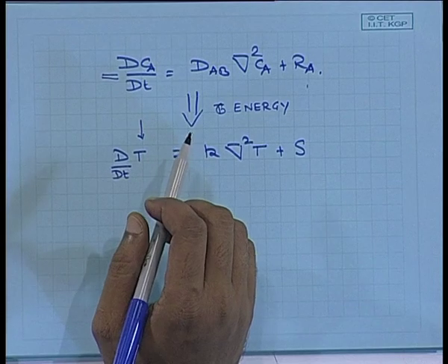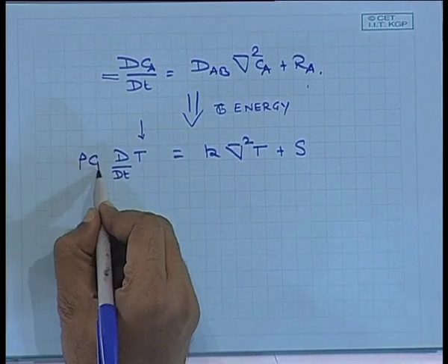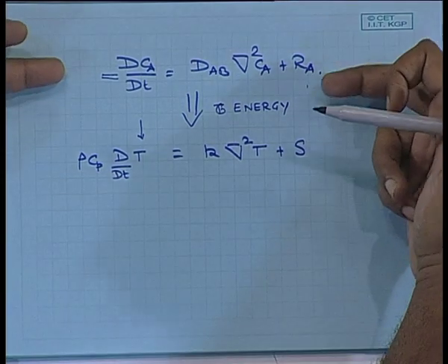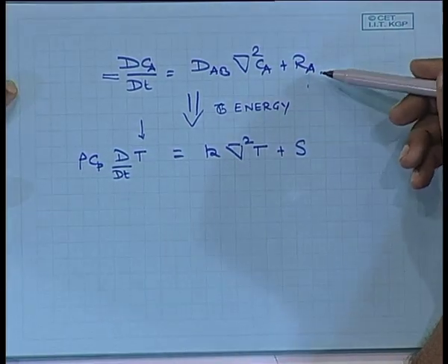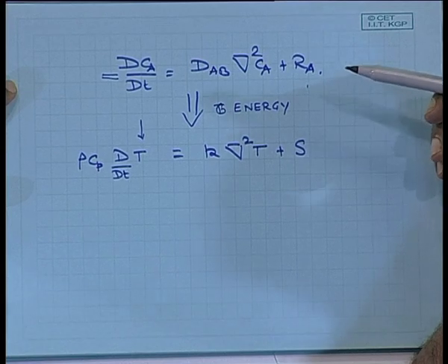So, is it mass times T minus reference temperature or mass times something else as well? Specific heat, Cp. So, the mass can be m, but the energy contained is mCpΔT, where ΔT is T minus reference temperature. So, in this case it would be ρ times Cp times T minus the reference temperature. So, what should I have as an extra term over here? Rho times Cp. Okay. So, this is one example of analogous treatment between heat and mass transfer.